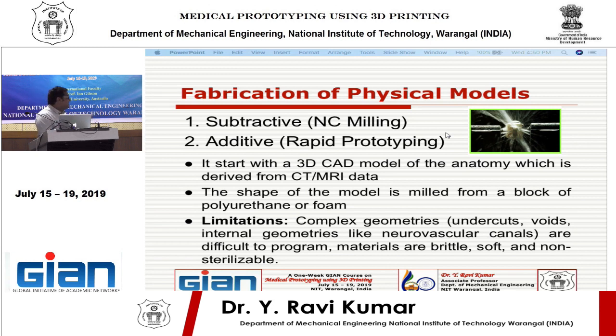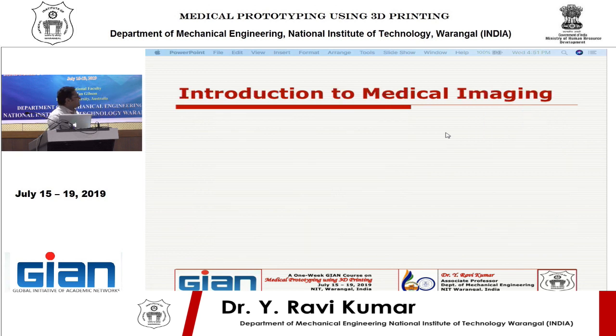The part may be brittle, or soft, or sterilizable. You have different materials now, so sterilization can be gamma, or it can be autoclave. Some of the materials can hold high temperatures and high pressures, so you can even go with autoclave sterilization. That is wonderful once you come with the route of 3D printing, which you may be missing once you go with the traditional NC practice.